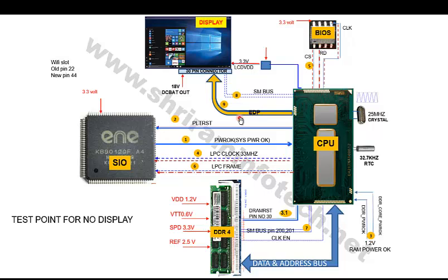Suppose one of the signals is missing. Basically, you wash the motherboard, remove the battery, wash the motherboard, and heat the motherboard. You can heat the motherboard using an oven, or using a BGA machine or hot air gun, because sometimes there may be dry solder or a bridge contact between the chips, which can be resolved by heating.